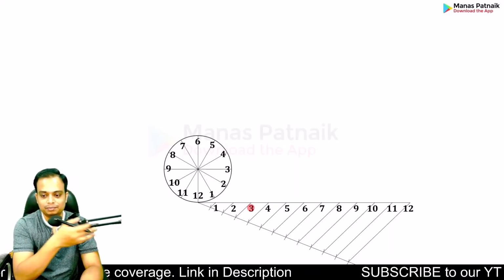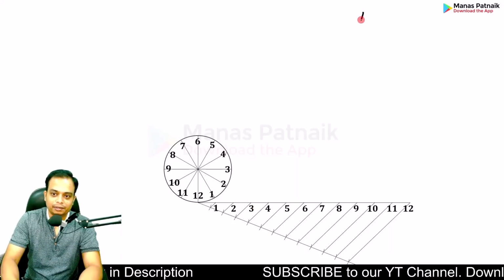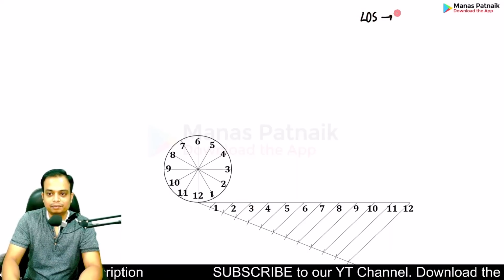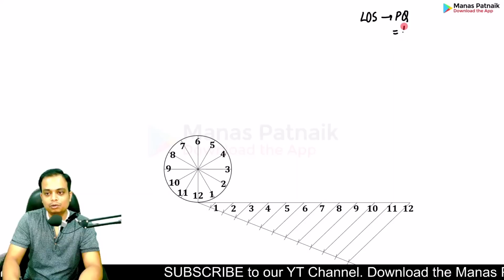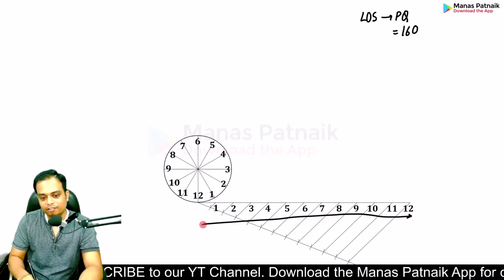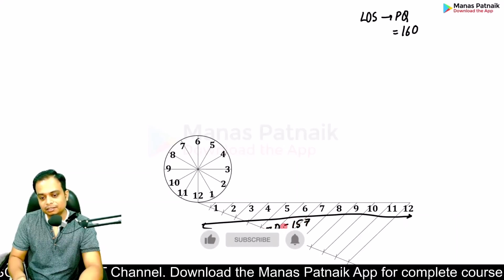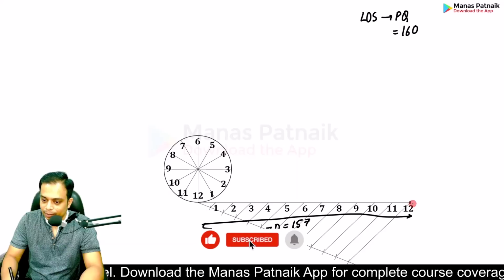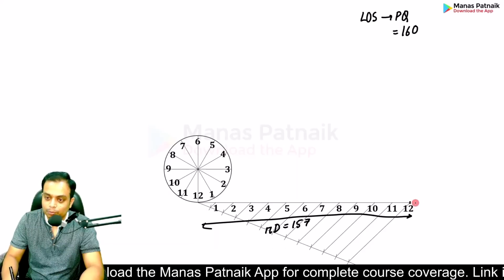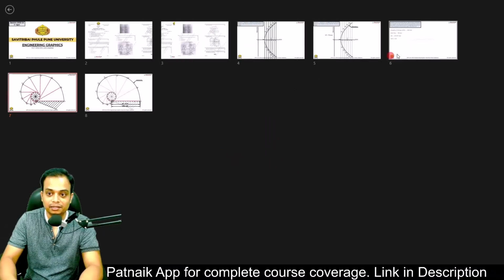Anyway, now what? Look, the length of string has been given. How much? PQ is equal to 160 millimeters. How much is this? The line that we have just made is 157. That is pi d, the circle circumference. So point P is going to be slightly beyond this, not point P, but point Q. Please don't make this mistake.